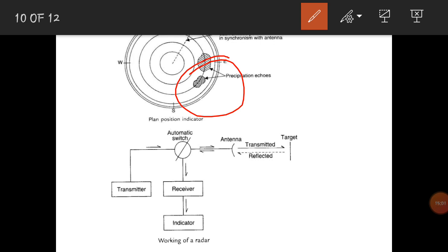The most successful technique for improving radar rainfall estimates has been to calibrate the radar with rain gauges. Simple techniques combine sparse gauge reports, that is 1 gauge per 1000 to 2000 square kilometers, with radar to produce smaller measurement errors, that is 10 to 30%, than either system alone.